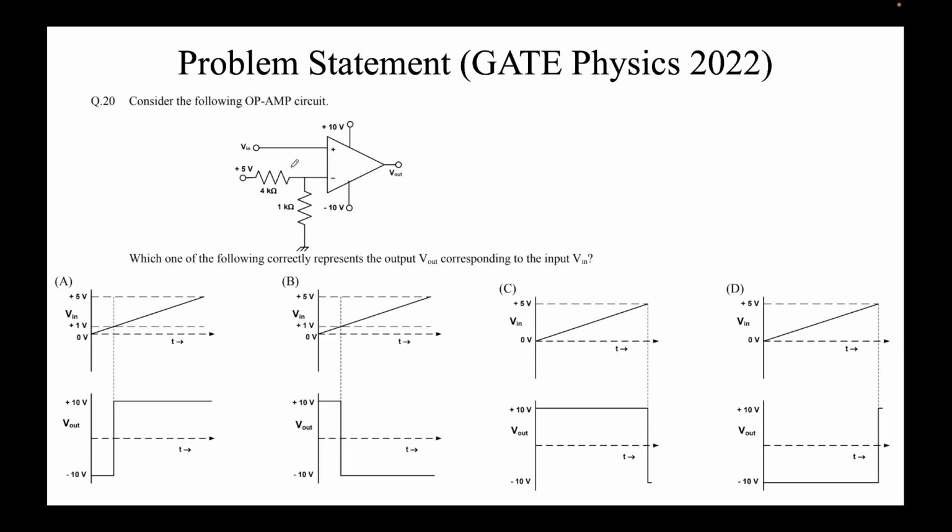Okay, I'll move forward and we'll solve the simplest problem that you can get with an operational amplifier. Whenever you're solving problems, you must identify a few things first. You must check whether the feedback network is there or not. First check, always: feedback network present or not.